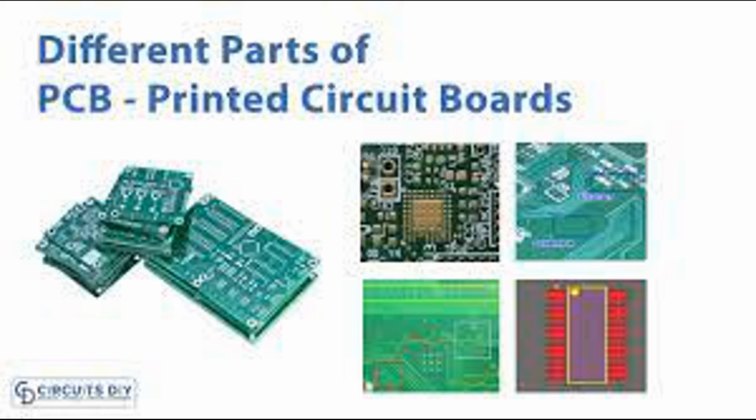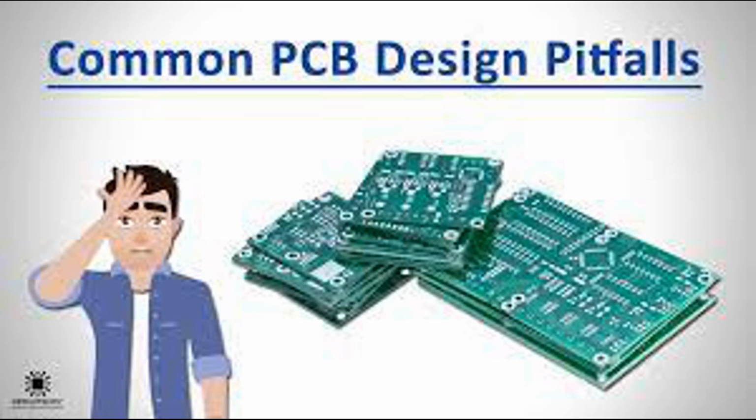Copper thickness. The thickness of the copper layers can vary depending on the PCB's design and intended application. Common copper thicknesses for PCBs include 1 ounce, 2 ounces, and 3 ounces per square foot. Thicker copper layers can carry more current and dissipate heat better but may also increase the cost and complexity of PCB fabrication.